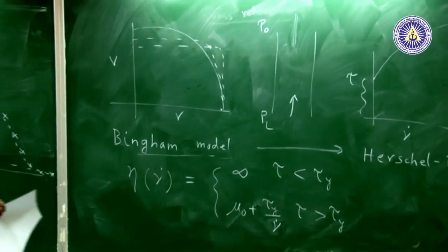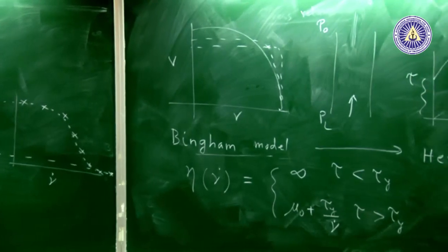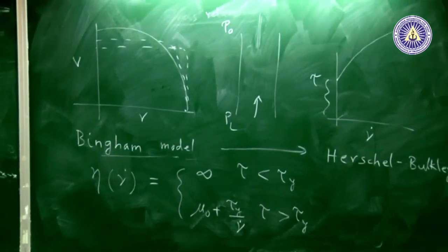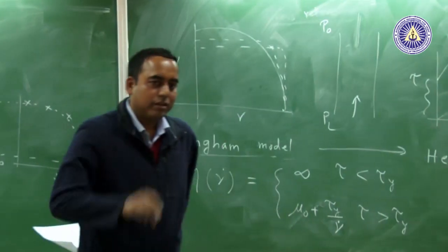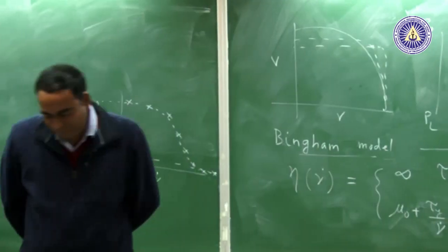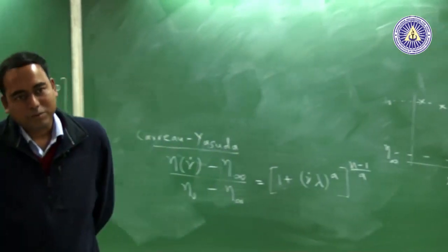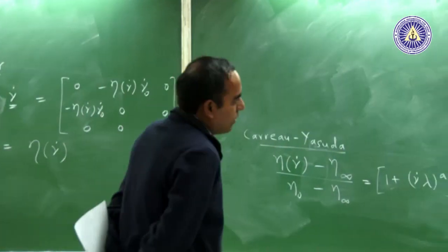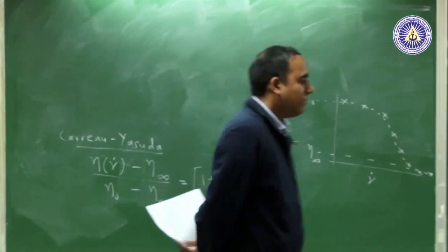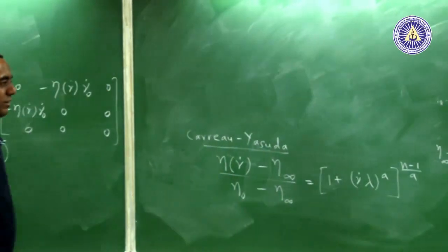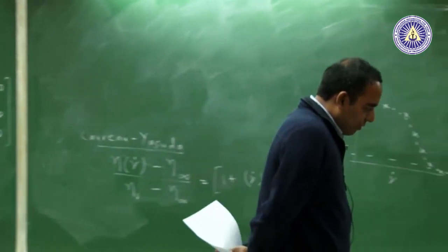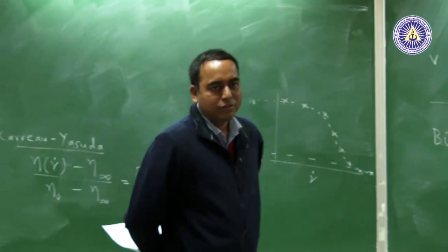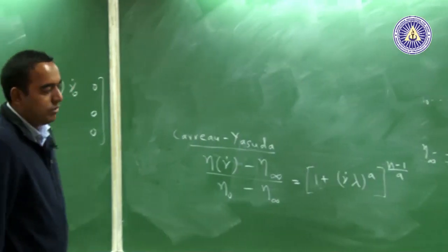The simplest thing that I have come across is that at tau e it just goes horizontally. There is no change in the stress. So it is constant, rate independent. That would be the simplest form of the Bingham, with zero viscosity. But typically in chemical engineering we have some viscosity, it flows with something. I think it is important for gels, and gels too do have some viscosity after the yield stress.